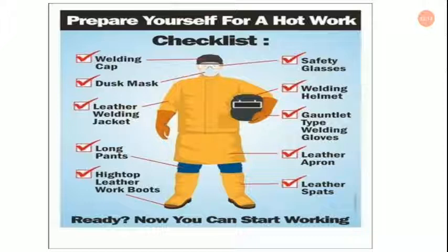So you have to keep your head out of the fume plume. You have to use mechanical ventilation or local exhaust at the arc to direct the fume plume away from the face. If this is not sufficient, you have to use fixed or movable exhaust hoods to draw fumes from the general area.